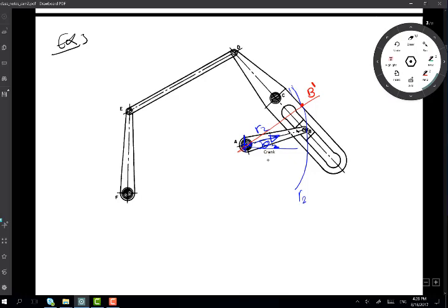This is the information I have. I'm giving you this new position of theta 2, given numerically: theta 2 is 60 degrees or 40 degrees or whatever value. Draw the linkage at the new position, draw this to scale, that's a graphical solution, and from this drawing, find the angles of different links.